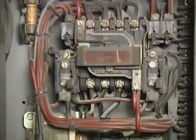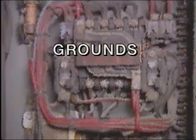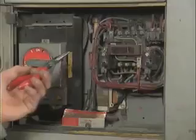If the visual inspection does not result in finding the cause of the problem, the next step, generally, is to take electrical test measurements. Three common faults you can test for are grounds, opens, and shorts. Test procedures for each of these problems are covered in some detail in this unit in the topic called troubleshooting.